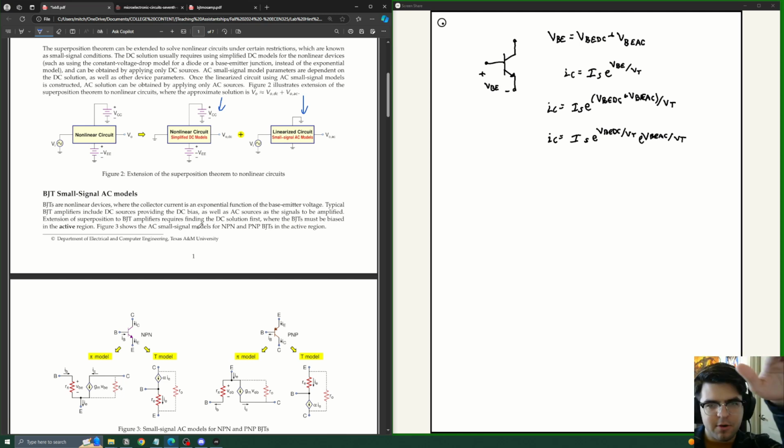We have our power, so it remains at a constant level, and the resistors are there that set all those voltages. There's nothing changing about it. It's how we biased the device. So we selected the sort of operating conditions, right? So this is a constant, and this follows the exact same form of IC. So this is the quiescent current, or the biased current, so we'll call this ICQ.